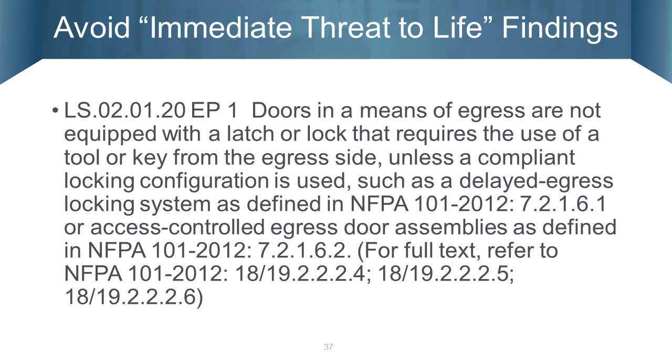So we must have a delayed egress lock on that door, or look hard to see whether it's truly needed as a means of egress, and whether it would be possible to remove the exit sign and not create a 30-foot dead-end corridor. Basically, although existing hospital occupancy can have an unlimited dead-end corridor, if you create it because of a magnet lock, you're limited to 30 feet because it would be considered under that new occupancy requirement, even if you had that magnet on prior to July 5th.